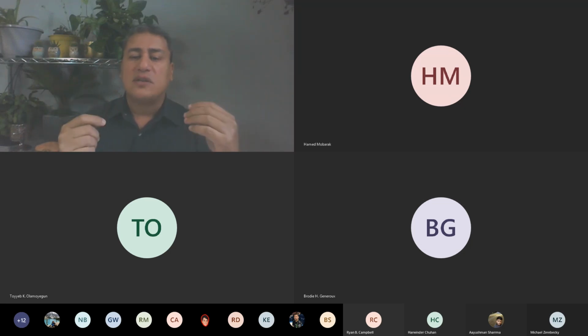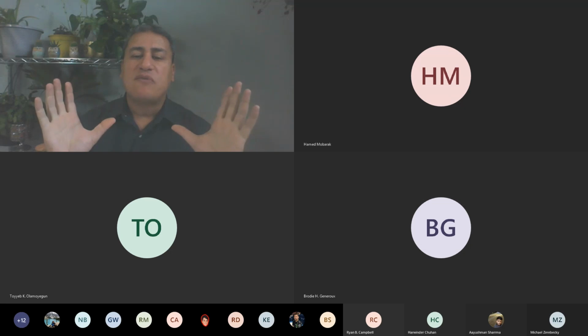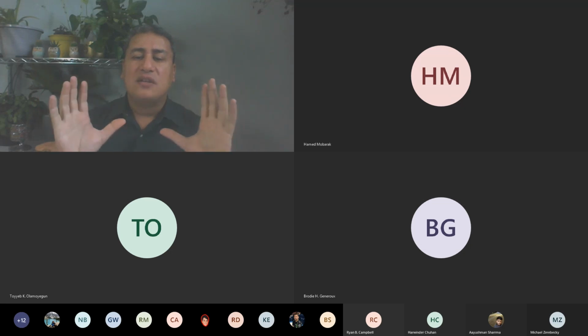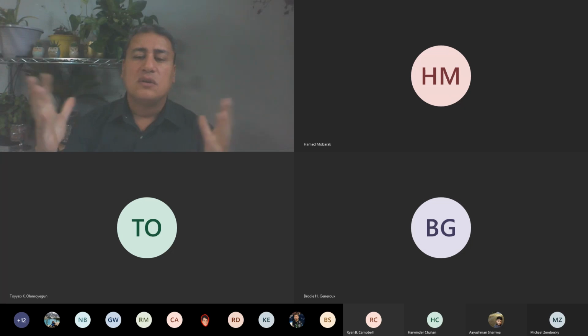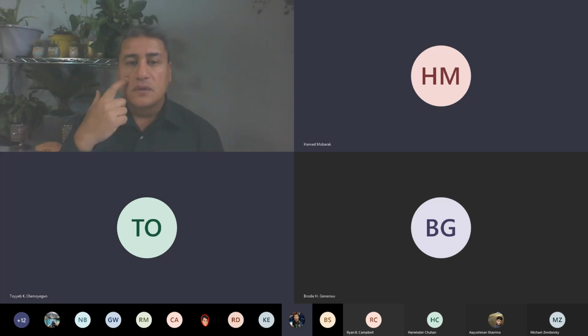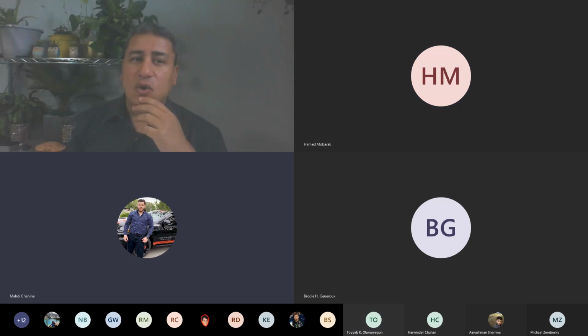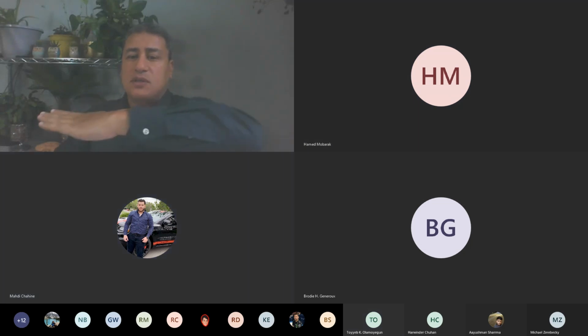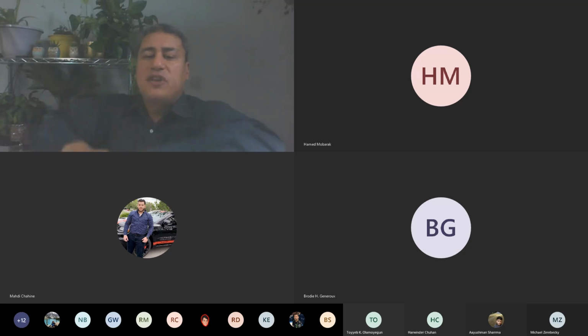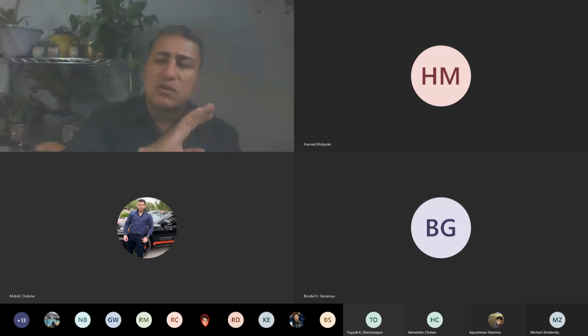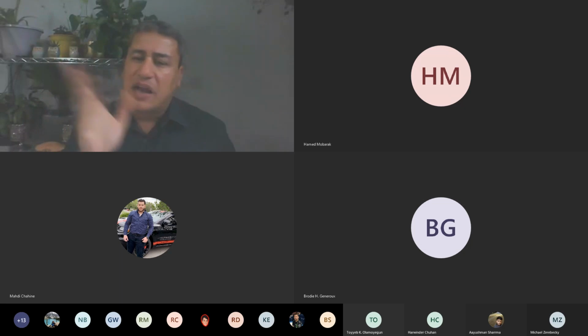So my question for you is, if you have beams sitting on top of a column, can they take care of the vertical load, the gravity load, or the horizontal load? What do you think? Gravity load. Gravity load, that's correct. So the beams, the way they sit horizontally on top of columns, take care of the gravity load only. The beam doesn't do anything for the lateral load, wind, seismic.